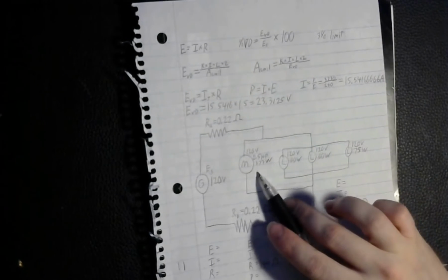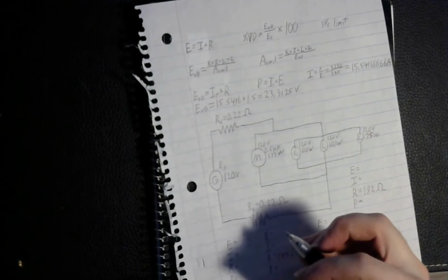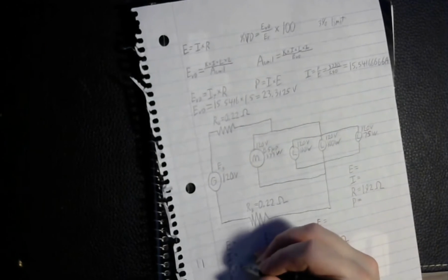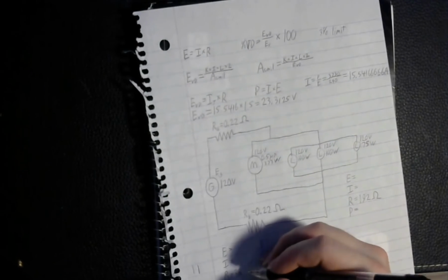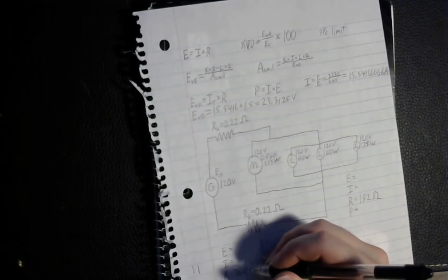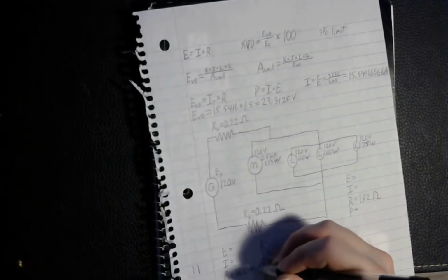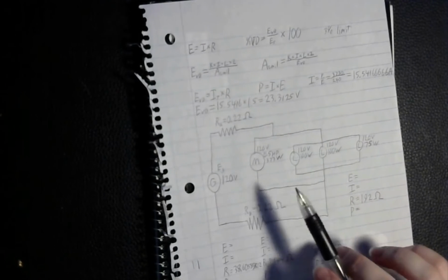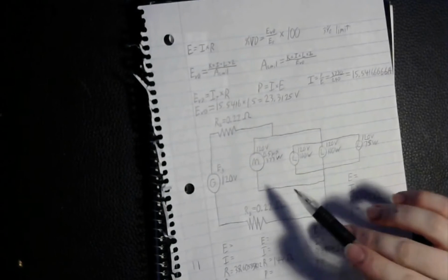Okay, so then we can figure out the resistance of that. So it's going to be 120 squared divided by 373. So that motor is going to have a resistance of 38.60 ohms. And that one's 589.812 ohms. So once you've got the resistances of all of these, since they're all in parallel, you can figure out what their collective resistance is.